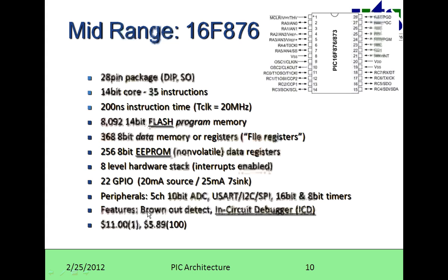Okay, and it is having some property called Brown-out detector. Brown-out detector means, suppose if a microcontroller is working with 5 volts, whenever the 5 volts decreases to some other 4.5 or 4 less voltage, then it will detect it automatically. The processor will reset the memory. Okay, it won't shut down, it will directly reset the program whatever is present in that one, and again it starts executing. If that is 5 volts, then it will start executing, otherwise it will stop the execution.